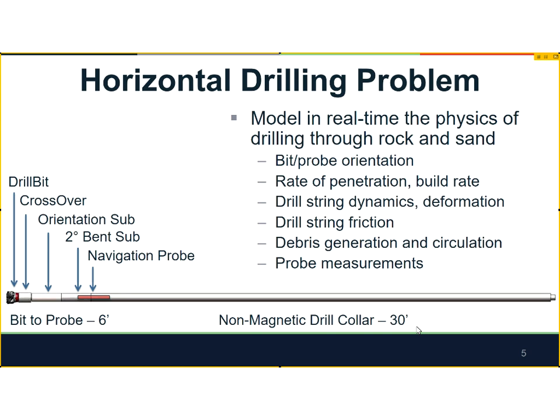And then if your rate of penetration changes, do you understand why? It can be unexpected geology or an issue with the machine. We're also modeling the dynamics of the drill string. And so we can have hundreds of these 30-foot steel drill pipes in the ground. And as stiff as they may seem, they do and will deform underground under high forces and torque.